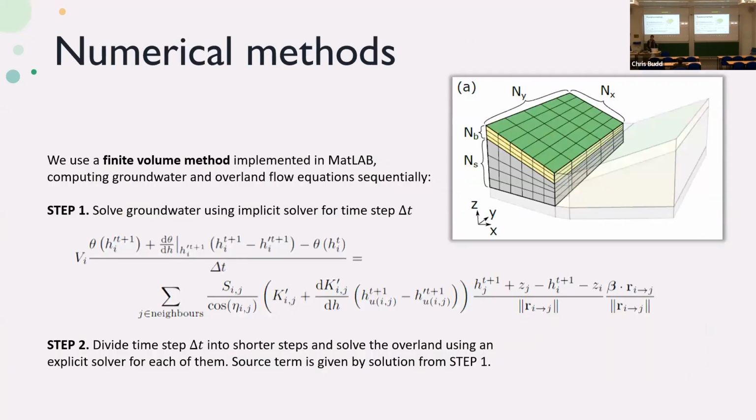Yes, sure. You're asking about this solver, you wrote a full 3-dimensional one, so you're including all the terms. I wrote a solver which is fully 3-dimensional, but you can make it 2-dimensional just by setting ny, the number of elements along the y direction, to 1.